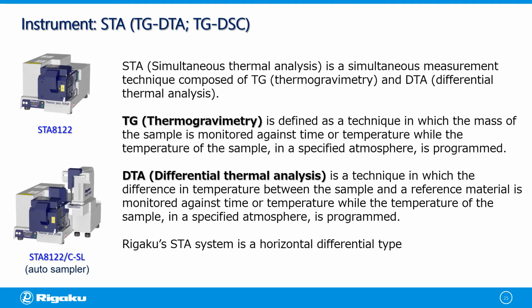while the temperature of the sample in a specified atmosphere is programmed. Moreover, the differential thermal analysis, or DTA, is a technique in which the difference in temperature between the sample and a reference material is monitored against time or temperature, while the temperature of the sample in a specified atmosphere is programmed. Rigaku's STA system is a horizontal differential type.